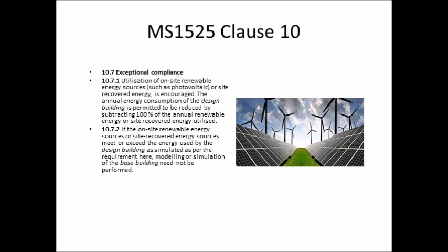So now if you can generate this 20 kilowatt hour per square meter per year by renewable energy using photovoltaics or wind turbine, then you can subtract. 120 minus 20, you get 100 kilowatt hour per square meter per year, and that matches the performance of the base building, so you are okay. So that's what it does, to encourage the use of renewable energy on site.